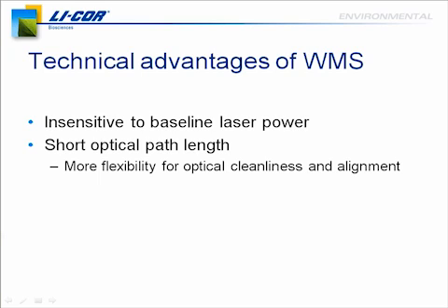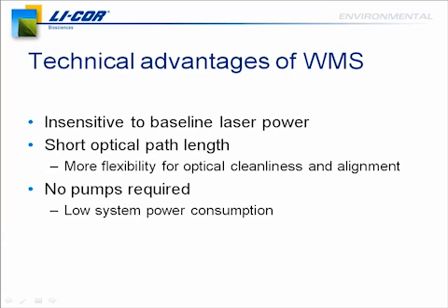One of the other technical advantages of WMS is that we don't have vacuum pumps, and that's really important in field instruments because of power consumption and pressure changes. Because to operate an instrument at a high enough flow rate to get eddy covariance measurements made in a closed path setting, you need a very high power consumption vacuum pump. So the open path analyzer gets away from that and really makes the instrument a lot more field ready. So those are some of the things that are important about WMS and how it's implemented in the instrument. But like I said, there's a lot more there that you can hear about in a couple of weeks.